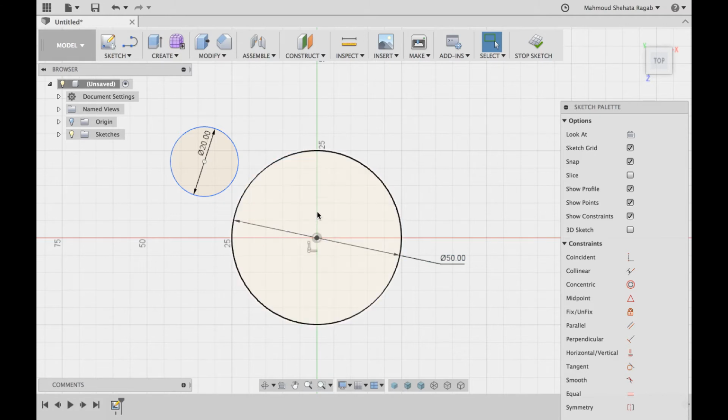Now let's turn our attention to the driven wheel here. The driven wheel will have slots, and these slots will determine how many stops, or rather how many dwells, the driven wheel is going to make. Now we have to decide how many dwells we want to have, because based on that we are going to decide how many slots we are going to model. So I'm going with 6. 6 is going to be okay. You can do more. I think the biggest driven wheel is around 18 dwells per one revolution. So think about it very reasonably.